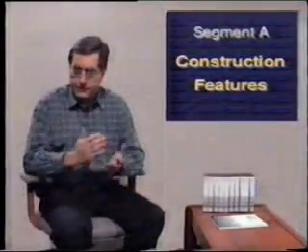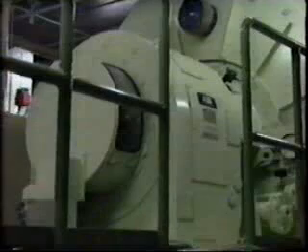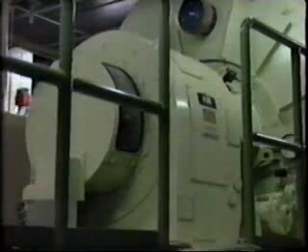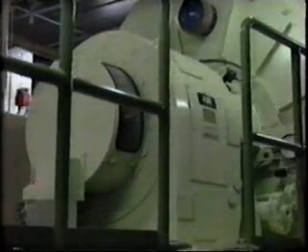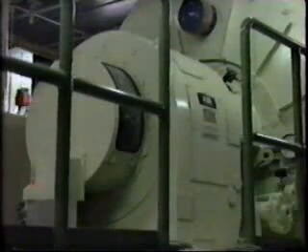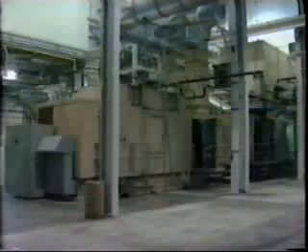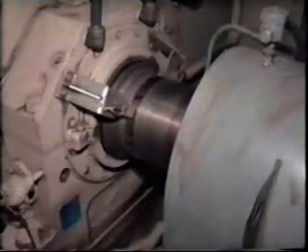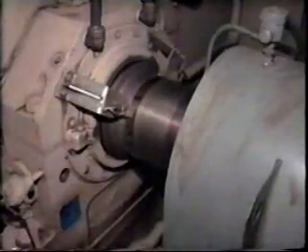An alternative source of DC excitation is from a shaft-mounted exciter. In this case, connection leads are run inside the shaft, and therefore no brushes or collector rings are required. The magnitude of DC current and voltage applied to the rotor windings is quite low, say 600 amps at 250 volts. Typically, the generator will be housed in a compartment like this. Access is provided to allow maintenance and inspection of the collector rings or brushless exciter. This particular generator is air-cooled, and the air is in turn cooled using water carried in these pipes.